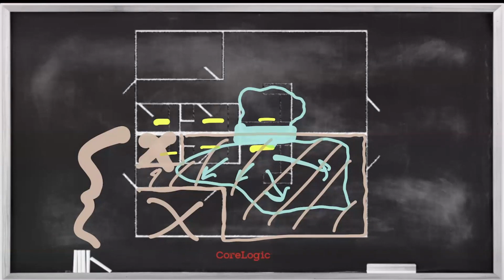Secondarily, then, what are my wet surfaces? Where the water exists and will be evaporating from, what are those surfaces? Are they highly porous goods? Or are we dealing with water that's in difficult to dry materials? Is that where my wet surface is? Now, notice that I'm stressing the wet surface because it's an initial evaporation load. I may have some materials that are affected that are lower in permeability, but if I've got wet carpet and wet pad on top of that, and I'm going to save those materials, then initially my evaporation load is going to be pretty high, right? So I'm going to use those wet surfaces that will be contributing to evaporation for that initial evaporation load. From there, we'll make adjustments based on my instrumentation, based on what we see for progress as we move through the project, right?